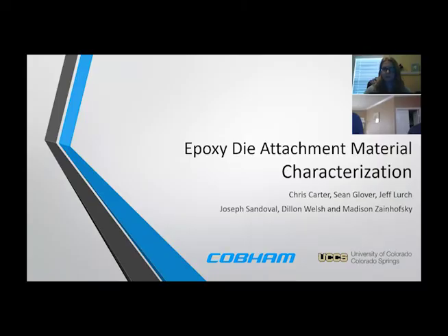Hello, this is Dylan Welsh. I worked for Cobham over the summer of 2019. I worked in finite element analysis and modeling of Cobham products to make lifespan predictions of Cobham products. The big important part of that phase was the epoxy underfill material that they use in their products. They use it to combat things like solder fatigue and die cracking.